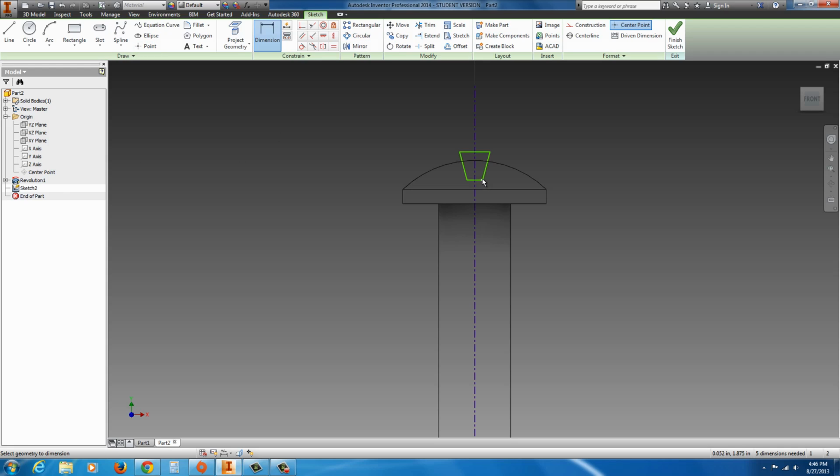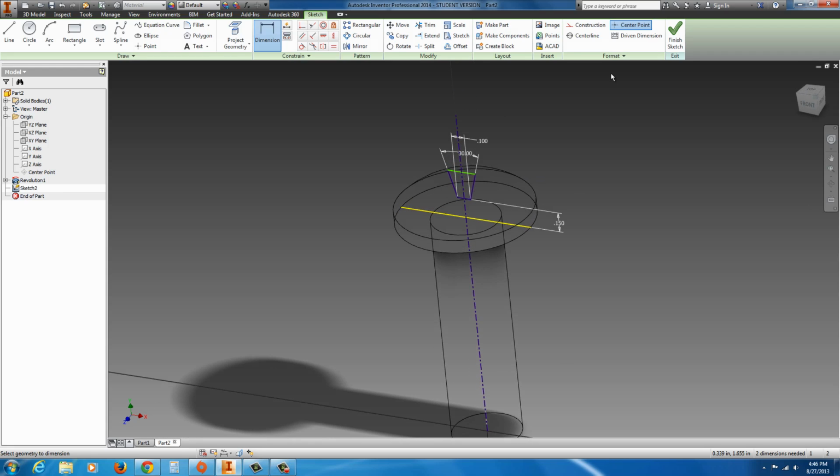Now we could go to dimension from this bottom edge of the cutout to the bottom edge of the bolt. That's going to be 1.5. Oops, I'm sorry, 0.15. There we go. And then dimension between the 2 angles, right in the middle there, 30 degrees. And then dimension both vertexes, the corners here. Drag that up, that'll be 0.1. Now this could just be left floating out there, because as long as it passes beyond the extension of that extrusion, we're in good shape.